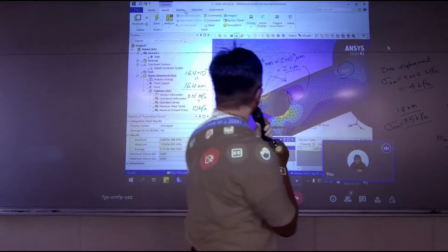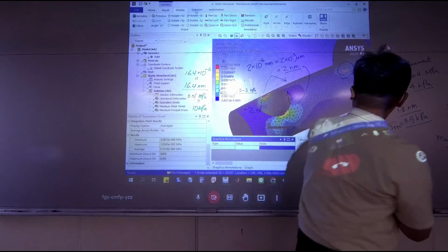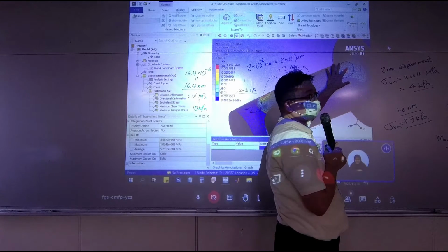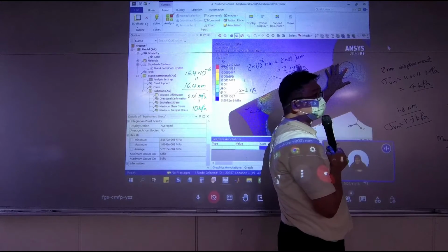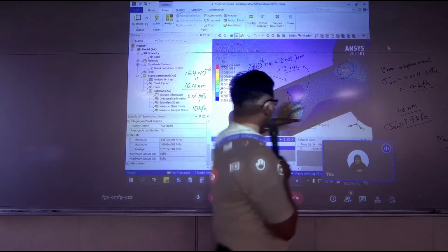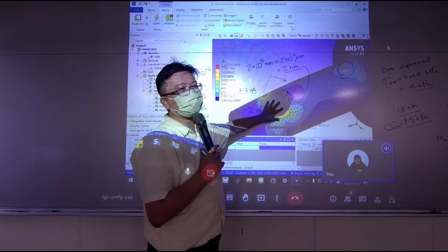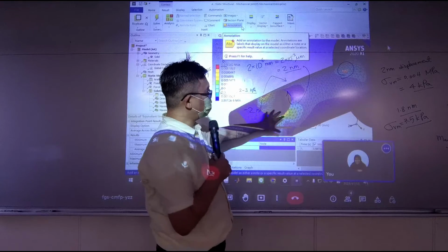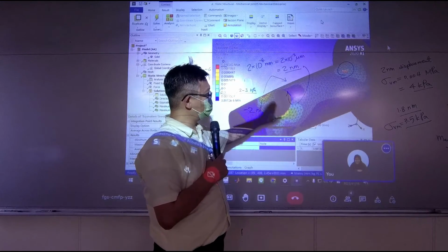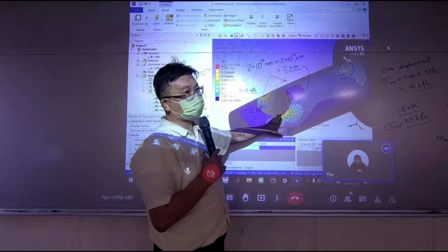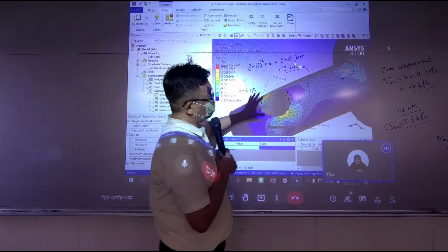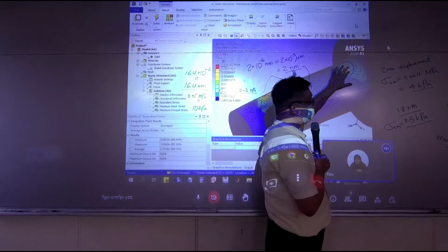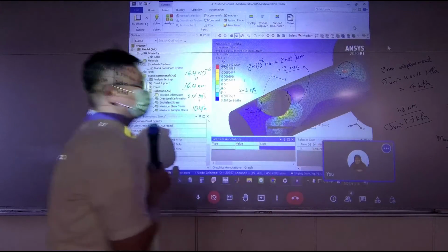So similar to what we had earlier. It didn't change much for this area. Or it could be even smaller stress, because right here it becomes so weak. All the shear force generated here is trying to create bending at this position. And over here, the original place, the stress becomes maybe a little bit lower.